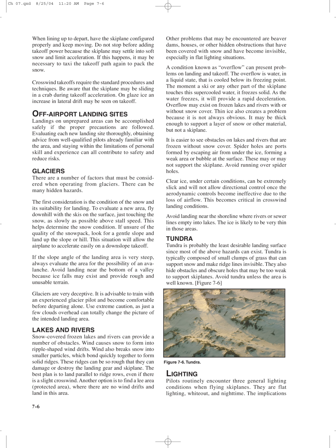Off-airport landing sites. Landings on unprepared areas can be accomplished safely if the proper precautions are followed. Evaluating each new landing site thoroughly, obtaining advice from well-qualified pilots already familiar with the area, and staying within the limitations of personal skill and experience can all contribute to safety and reduce risks.